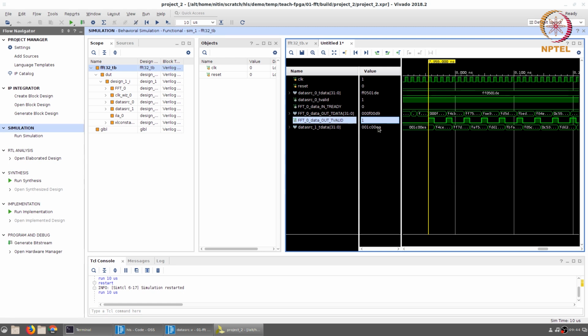Remember that the D9 and the EA are both referring to the portion that is in the fractional part, because this is 16-bit data with an 8-bit fractional part. What about the next output, F4CB? Well, the expected output was F4CE. 0328, the expected output was 0334.